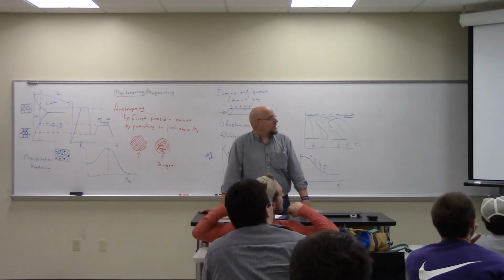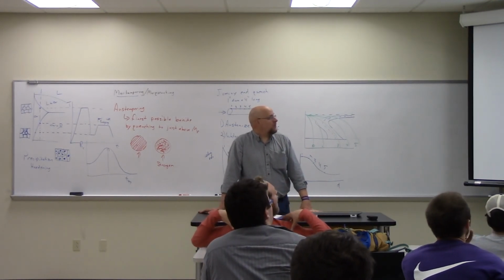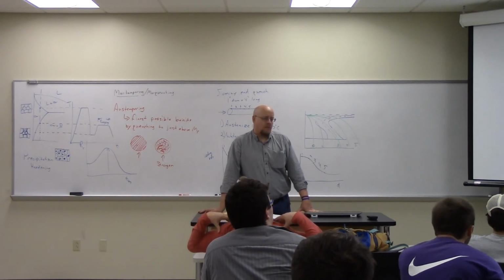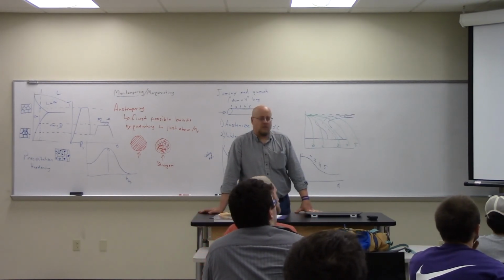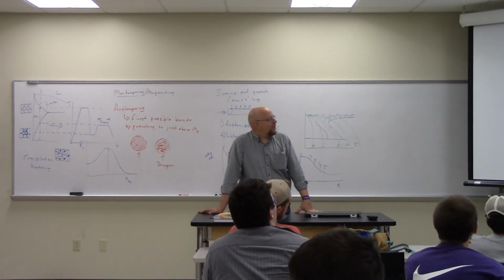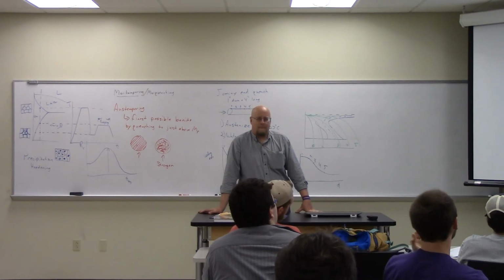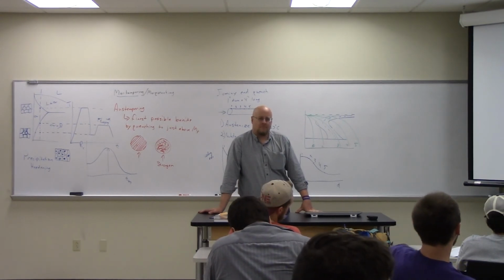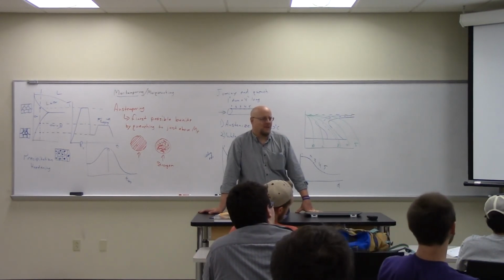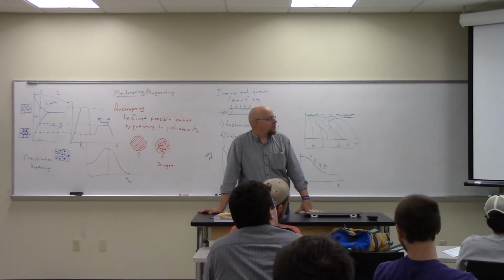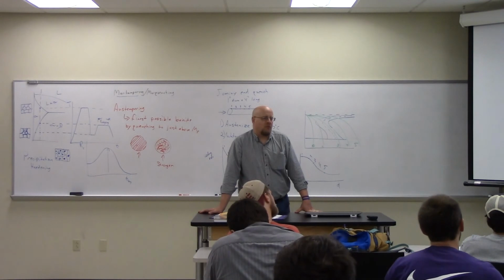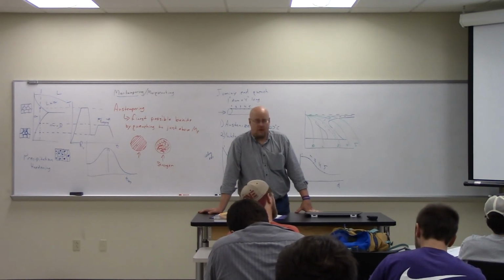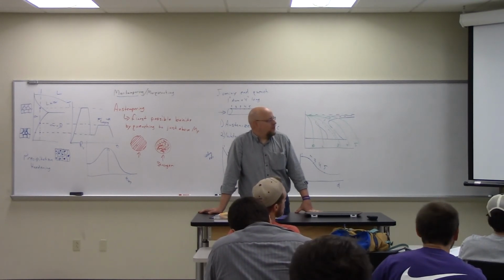Okay, part D, repeat A through C for a steady rate of cooling in exactly 1 minute. So D says 1 minute, E says 1 second. Okay, so what would that look like? But what did we answer for the first part though? The temperature at which it starts and what it forms. Temperature is 717 apparently, degrees C, and it forms coarse pearlite.